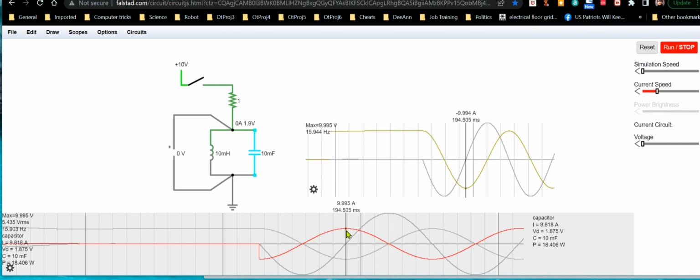But here, the inductor is demanding a higher and higher current to resist the decrease, so the capacitor is having to supply more and more current to try to discharge itself. That's why you see the voltage eventually come down to 0. That means the capacitor is flat now, but the field in the inductor is fully charged.